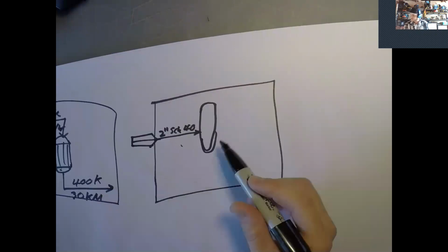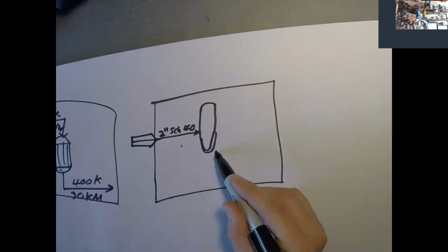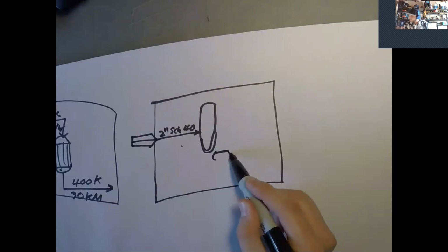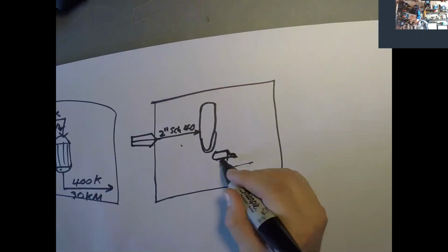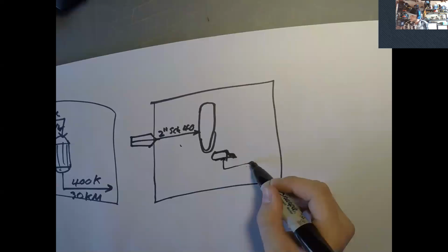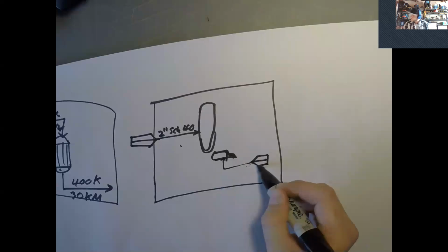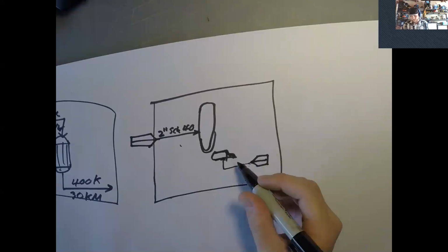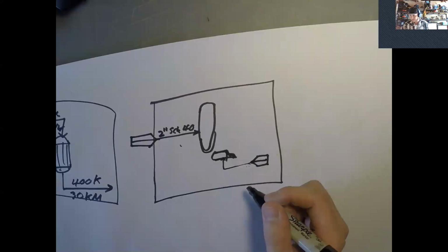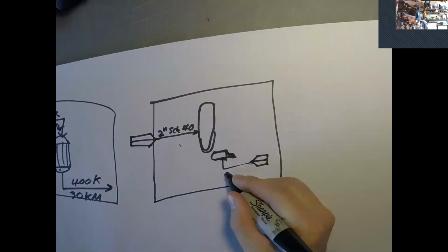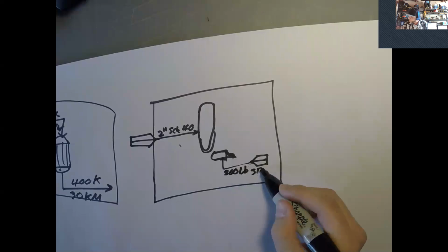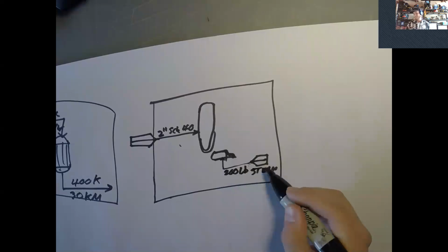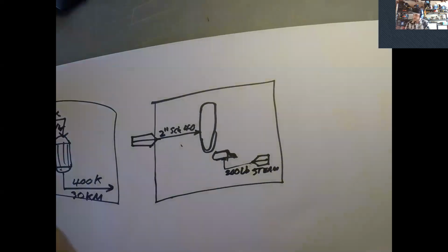And then for utilities, so again, let's say you have a reboiler at the bottom of this column. It's a beautiful kettle reboiler. So you got steam coming in. You would call out whatever this is. So let's say, maybe 200 pound steam. And it's kind of interesting in process operations.